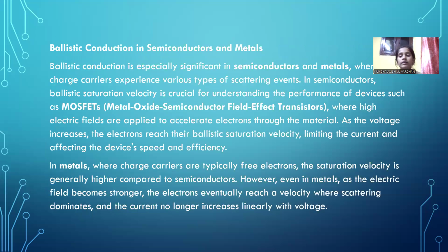Ballistic conduction in semiconductors and metals. Ballistic conduction is especially significant in semiconductors and metals, where charge carriers experience various types of scattering events. In semiconductors, ballistic saturation velocity is crucial for understanding the performance of devices such as MOSFETs, metal oxide semiconductor field effect transistors, where high electric fields are applied to accelerate electrons through the material.